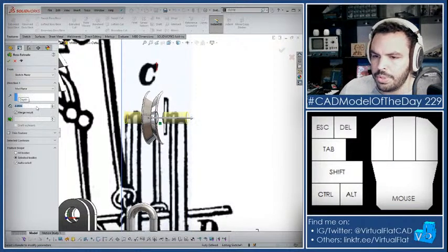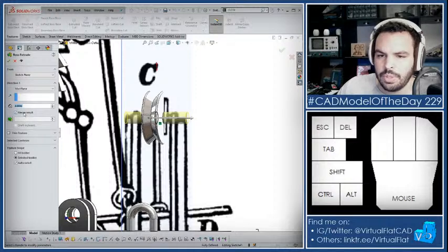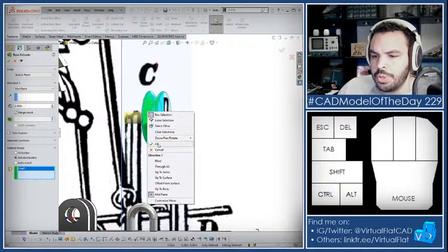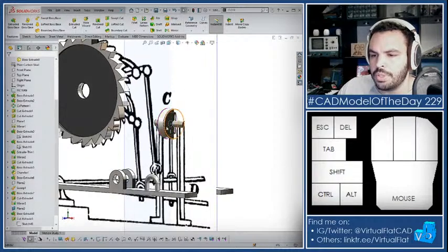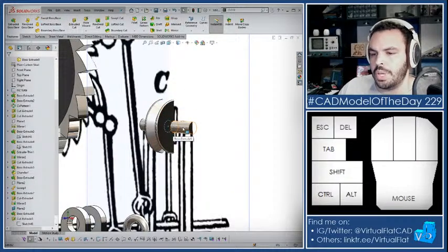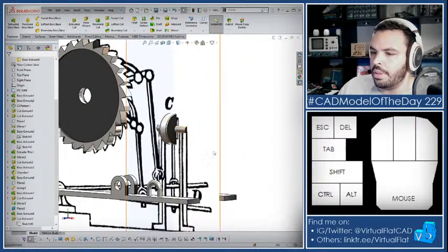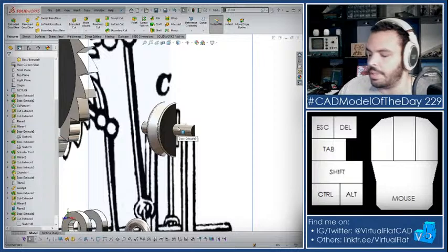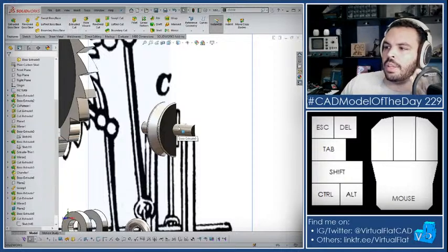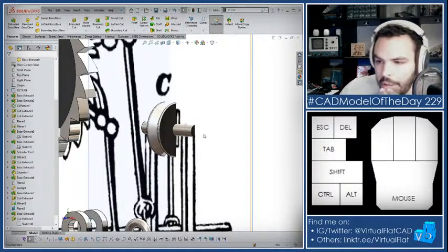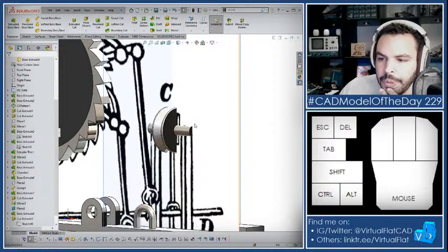Maybe 2 inches. And it might not be bad to just merge it with this, since there's no reason that the pulley needs to rotate independently of this bar. It might have to in real life, if you need to put a bearing to make this thing actually run smooth. But at least for the mechanism simulation, that will pose no issue.